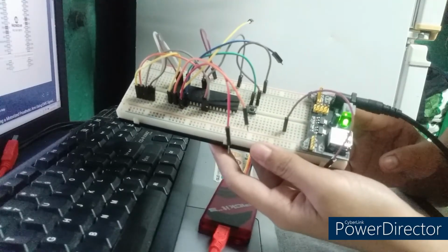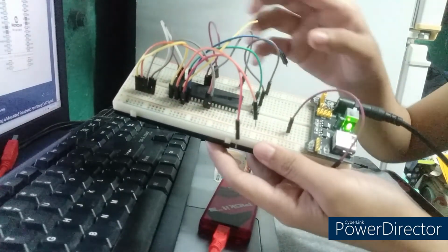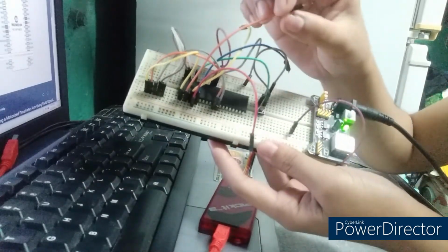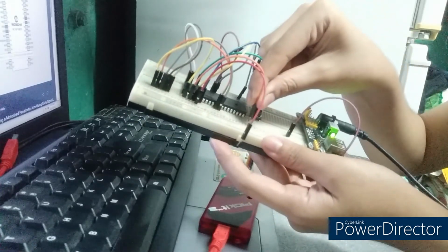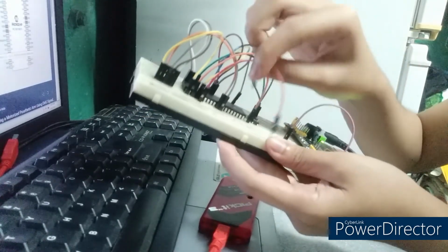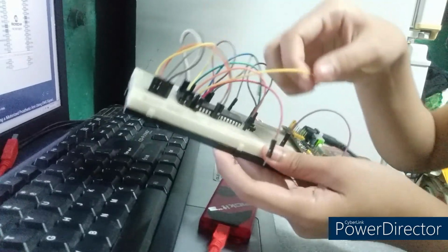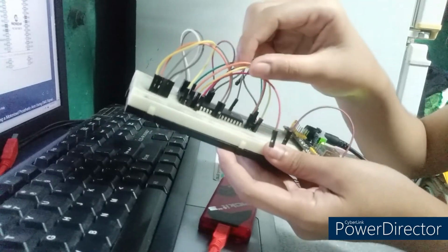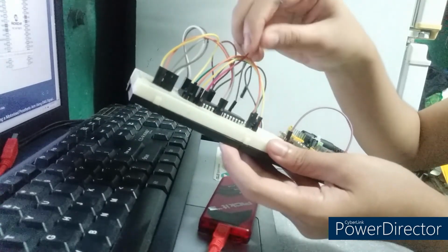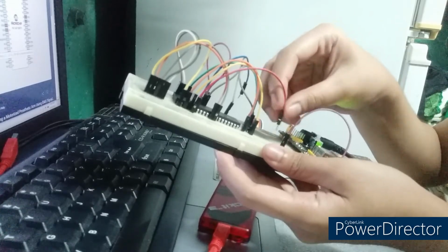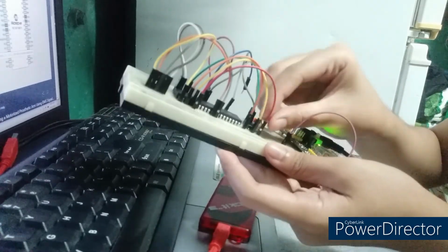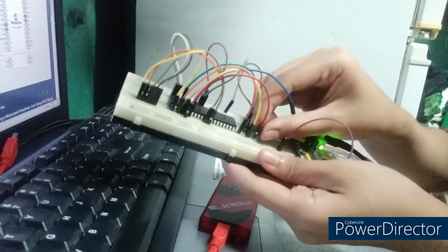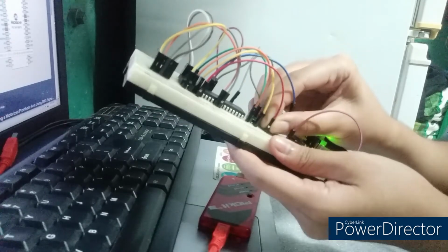Now to set up our circuit, we will be connecting 4 wires in our IC. For RA1, it will be the orange wire, and for RA2, the yellow wire, so let's connect it here as well. For our RA3, it is the red wire, on this part of the breadboard. And for our RA4, which is for our LED4, it's in this part.